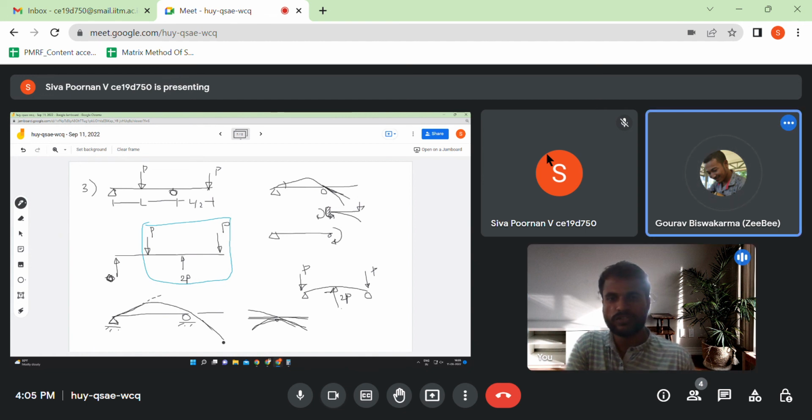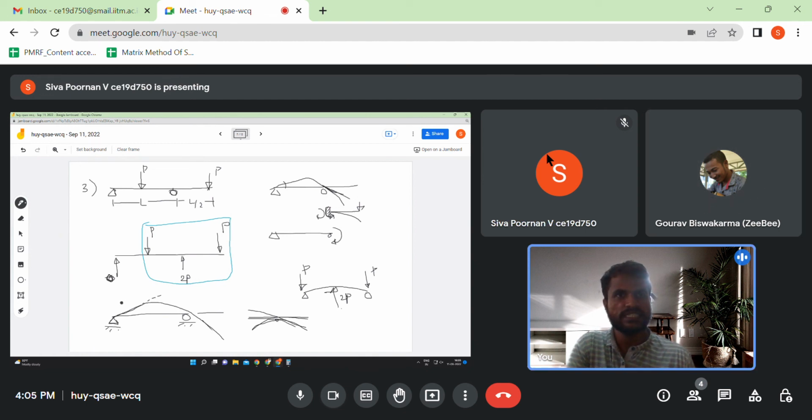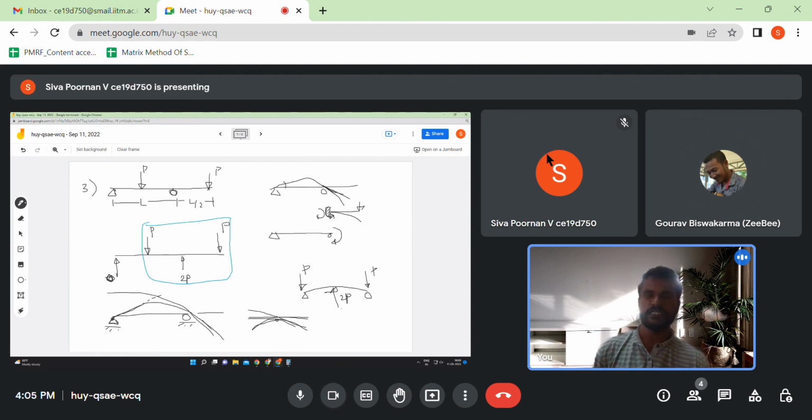Or the stresses or strains. It just says that the seesaw could have been something like this. It's just making it rotate and then come here. It will rotate freely like a rigid body and come here. That's what the support is doing, nothing else. It's just ensuring that the displacement at this point is zero.